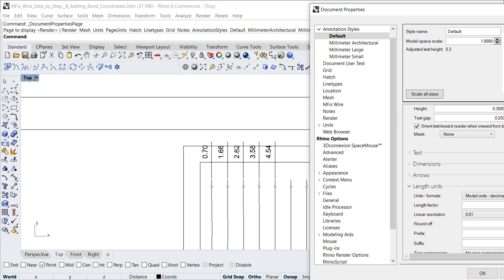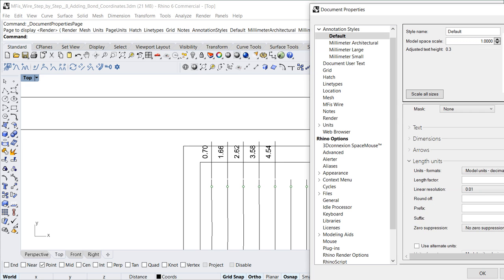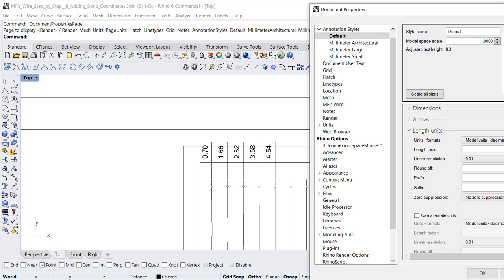Okay, and now you might rather prefer to have it in microns. So what we do, under length unit, we change it to microns. Here we have the model units of the document which are millimeters. Would be great if we could change it here, but unfortunately micrometers are missing. But what we still can do is just multiply the value by 1000 and click apply. Okay, so we now always have 2 zeros at the end of the number.